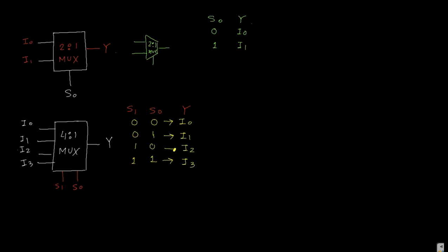That means if you write the expression, Y becomes S1 bar S0 bar I0 plus S1 bar S0 I1 plus S1 S0 bar I2 plus S1 S0 I3.